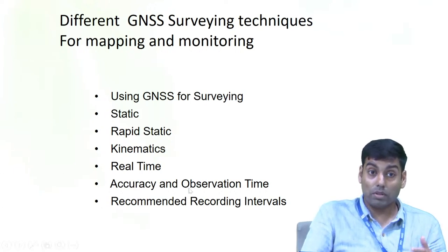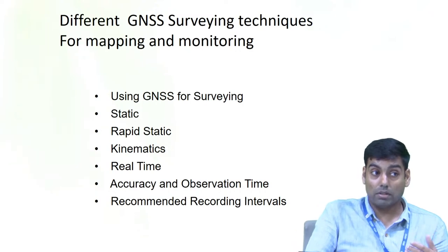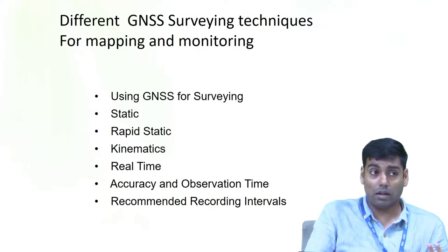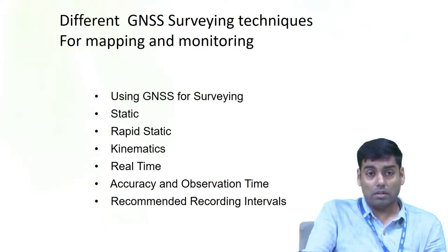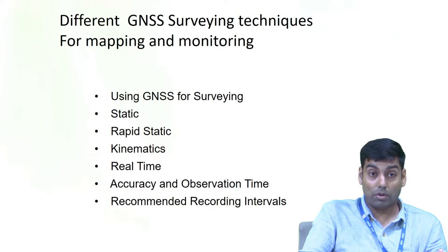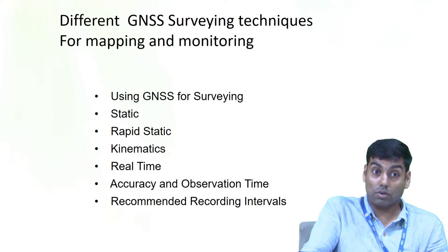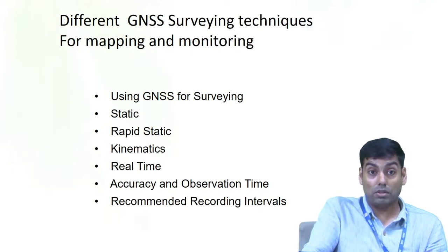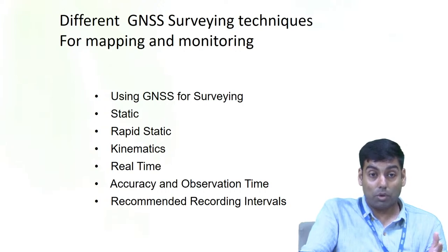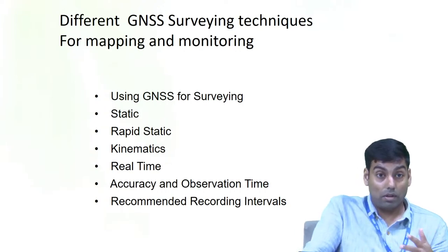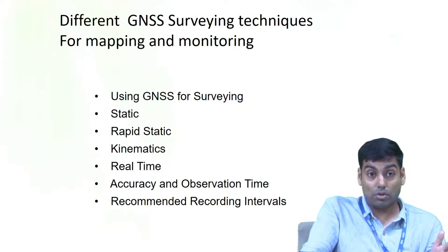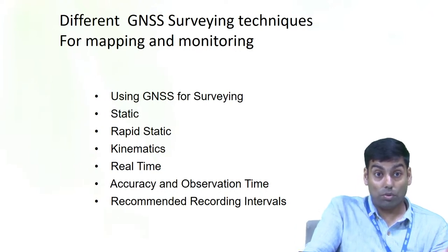And when you are going for this GCP, ground control point, half an hour or 1 hour of data is sufficient, because your satellite has an accuracy of about 5 to 8 meters. If I talk about LISS-4, it is 5.8 meter resolution. Cartosat-1 is 2.5 meter resolution. There are different generations of the Cartosat series also, with better resolution of 0.6, 0.7 meter. So it is very high resolution.